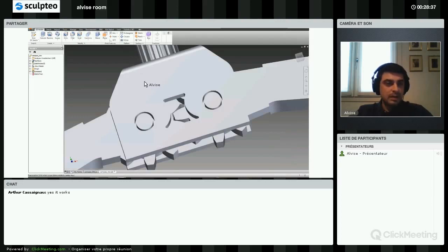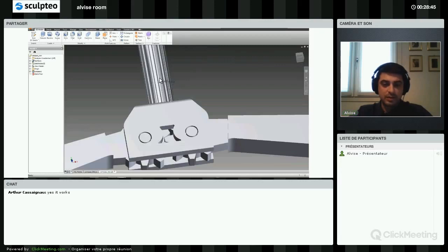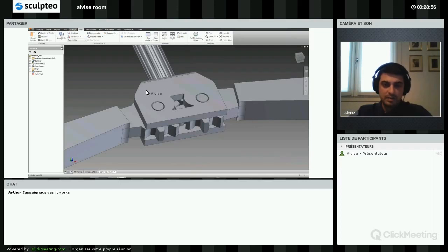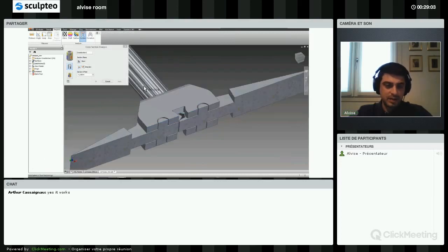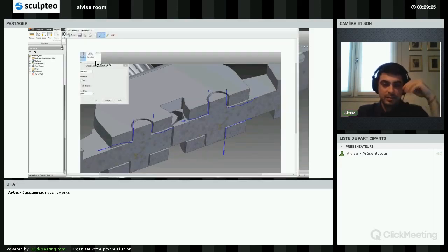And for the second problem, between the gears, applying again the section view, we provided a different architecture, so that in this way we have a straight escaping path for powder. As you can see here, now the powder is out from the top and the sides of these moving parts. There is no longer any place where the powder can get stuck in a blind corner as before. So we printed this correctly in polyamide, and yeah, we learned something from this.